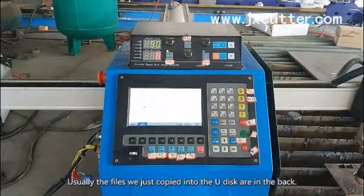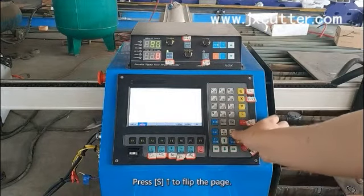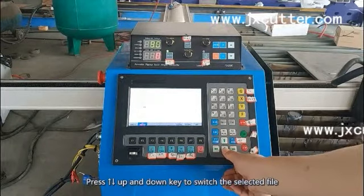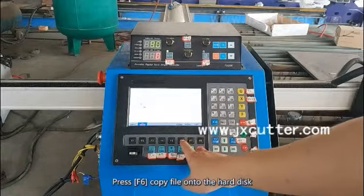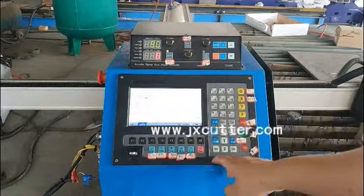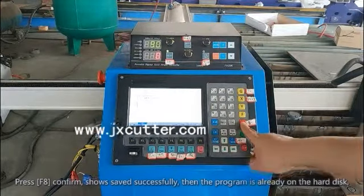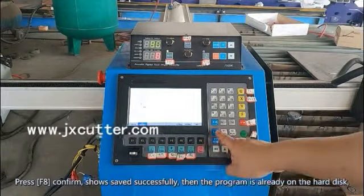Usually the files we just copied into the U-Disk are at the back. Press S to flip the page. Press the up and down keys to switch the selected file. Press F6 to copy the file onto the hard disk. Press F8 to confirm. It shows saved successfully, then the program is already on the hard disk.